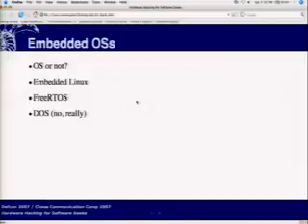Now, the next thing you'll need in making your own embedded device is to decide which way to go, whether or not you want an operating system at all. Some things that can determine this is if you have real-time deadlines that you have to meet. Let's say you're doing some sort of control application for an airplane, and if you don't send a certain signal every 500 milliseconds, the engines stop. Basically, that's a hard deadline.